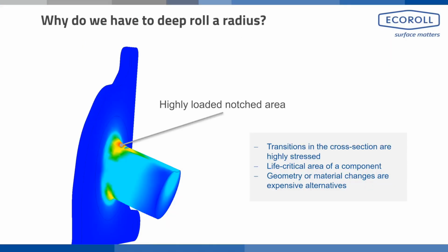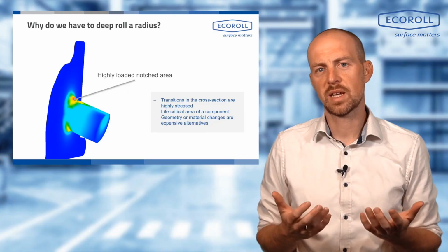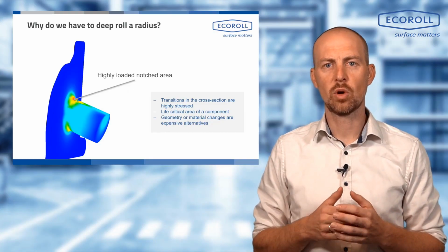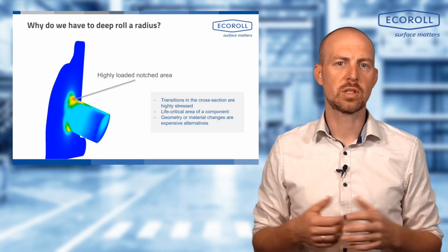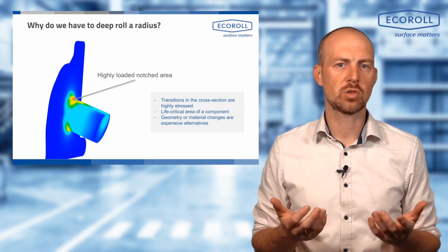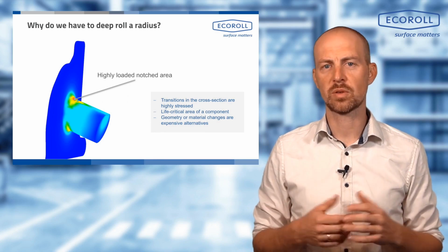We have simulated this here. You can see it in a simulated wheel carrier where we have introduced a radius. We are applying a defined force to this wheel carrier. And what we naturally see is that right at the top, where the highest tensile stresses are, there is the greatest load. A component will eventually crack under dynamic load at this point.